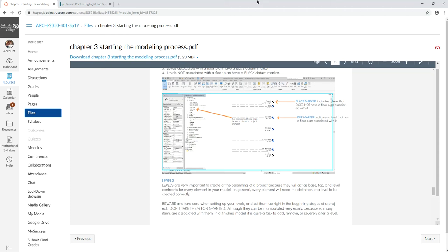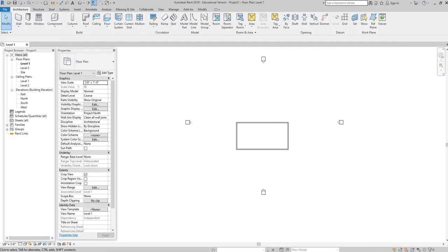And so that 3D nature that Revit has built into the program is different from other computer-aided drafting programs. The ability to have that 3D model at the same time you're doing 2D drafting is defined by levels. So inherently, when you open up most Revit models, or templates, I should say, you have a couple of built-in levels. You have to have them in order for the software to function. So they have a couple of default ones you'll always see.